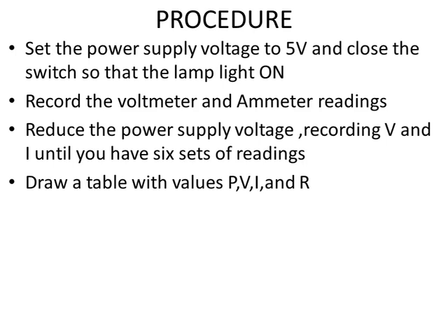You get it now? So you continue to reduce down your power supply, and as you reduce, you record your voltmeter and your ammeter, till you have 6 sets of readings. The first reading is for 5 volts. Then you have 5 other ones as you reduce your 5 volts. So after having that, you have your readings. So you'll be having your table.